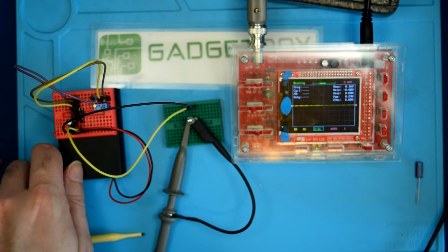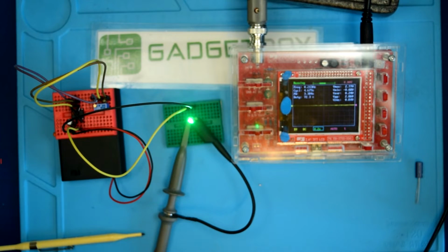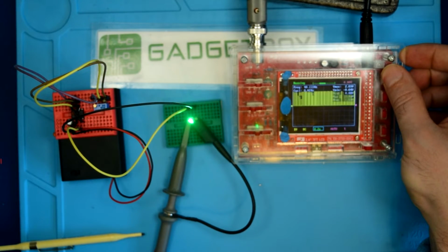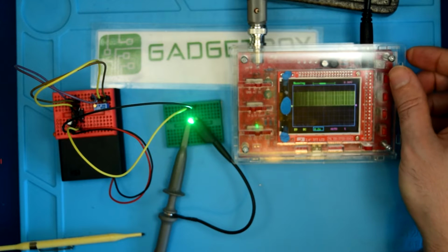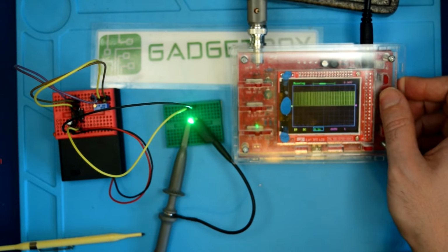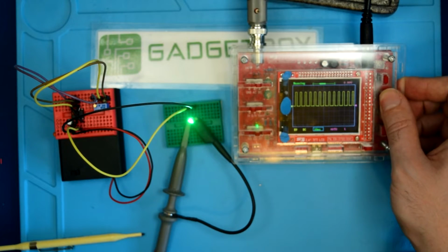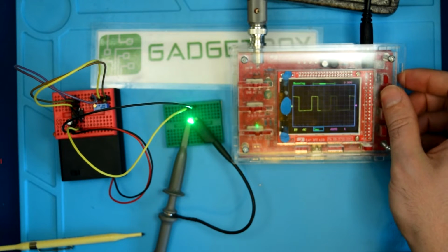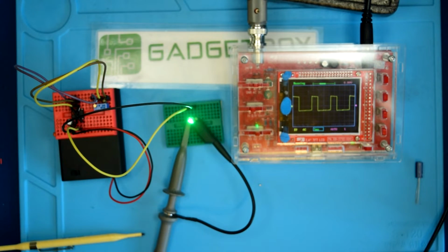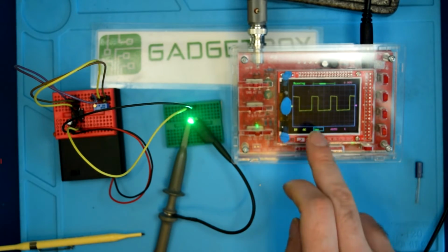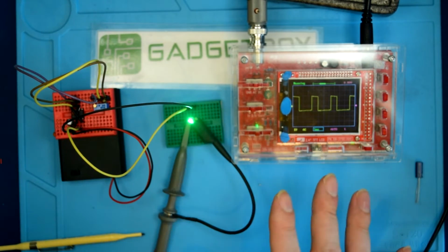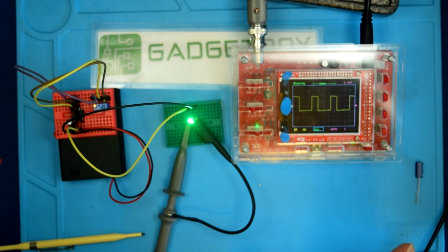All right, let's turn that back on. Now, you'll notice on the screen that there's... oops, come on, go away. There we go. Let's change our time base here, switch to AC coupling. We'll actually get a bit of a better view of the graph there. Ignore the transient sort of angles on that. That's just because I'm using AC coupling to view a DC signal, so it doesn't display quite properly, but it at least triggers, so it holds the display steady.